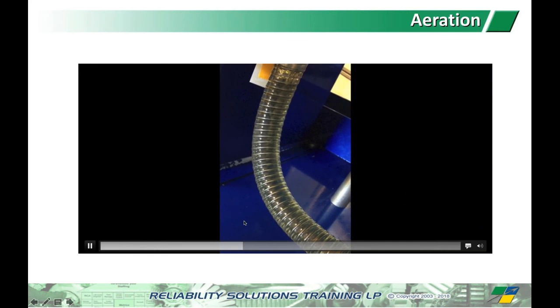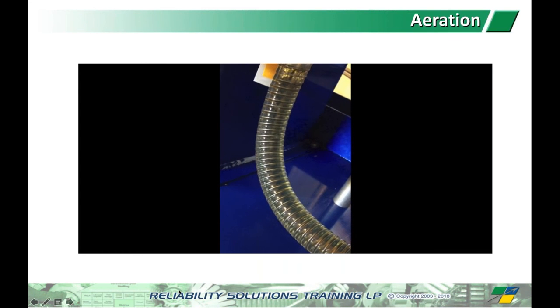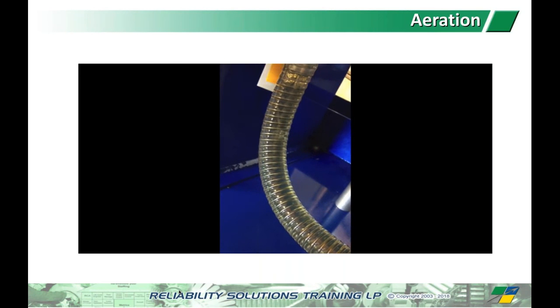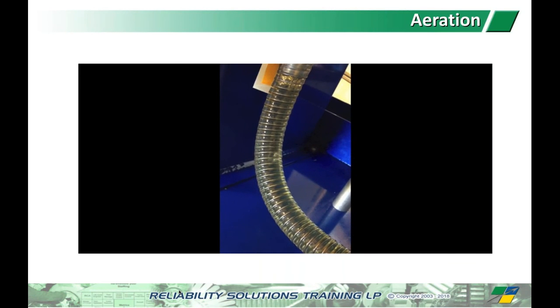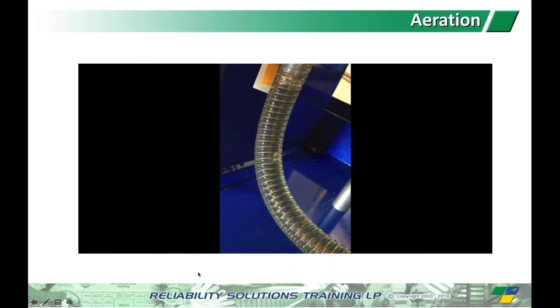See the air bubbles coming in? When they hit the pump, you can hear the little crackle. See that crackling sound is every time an air bubble. Of course, once one of these big bubbles slugs in there, it's a problem. And again, cavitation and aeration are major causes of pump failures and problems in hydraulic fluid power, breaking down the oil film and causing excessive wear and damage to our internals.